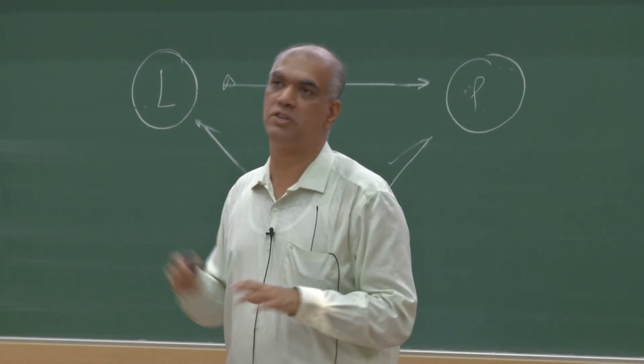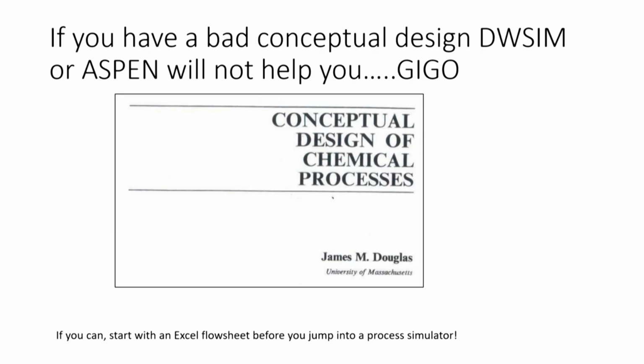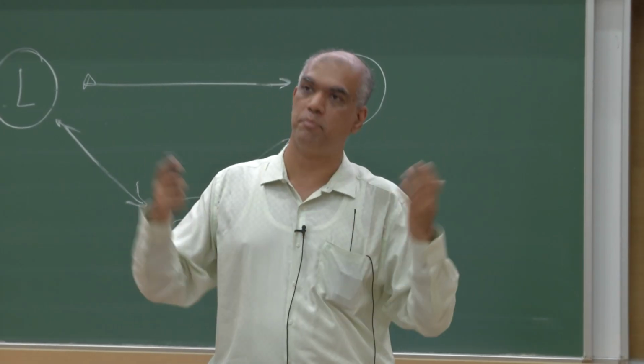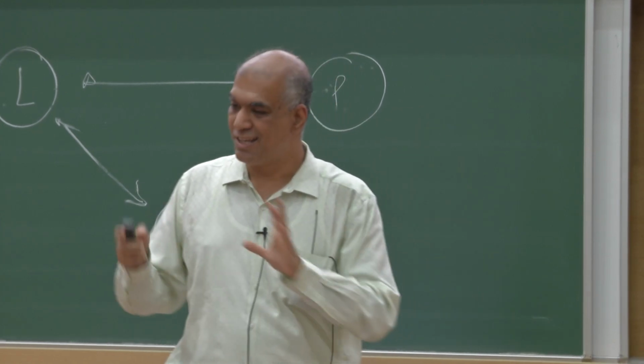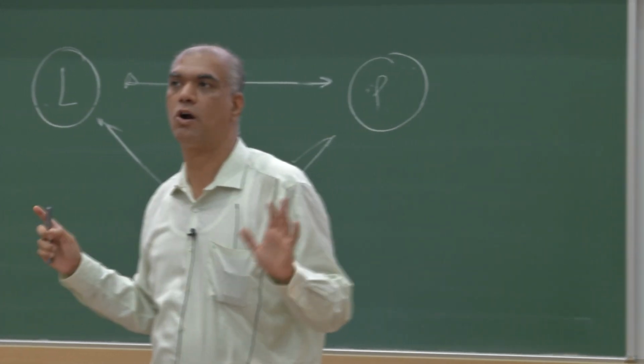So do a good conceptual design. This is a good reference because if you make a mistake, right, like if your concept is not sound, suppose you should be using distillation, but you're using liquid-liquid extraction for whatever reason, or there is an azeotrope, but a phase separation would have worked, but it's an azeotrope and now you are wasting a lot of time breaking it. So if you make a mistake at conceptual design, your Aspen or DWSIM is not going to save you.